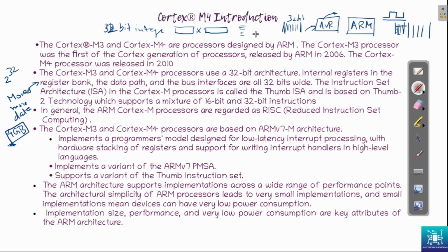So if you are aware of 8-bit assembly code and you are trying to multiply say two 32-bit numbers, you will know how tough it is, because it has to run a lot of extra logic to multiply those two numbers. In the case of 32-bit, it happens in one clock cycle, because 32-bit means that number is saved in the register, and the arithmetic logic unit of this particular controller, that is ARM controller, is capable of handling 32-bit arithmetic. So if two numbers come in of each 32-bit, in one clock cycle that operation is done. So this is clearly advantageous.